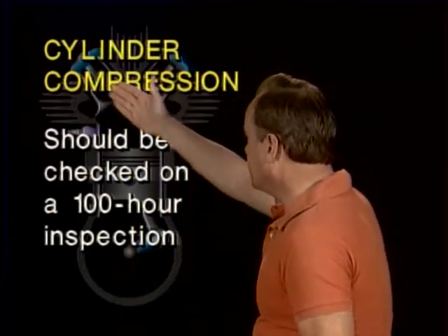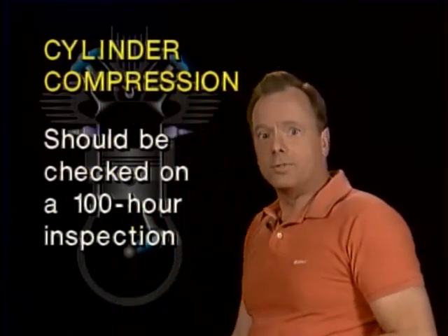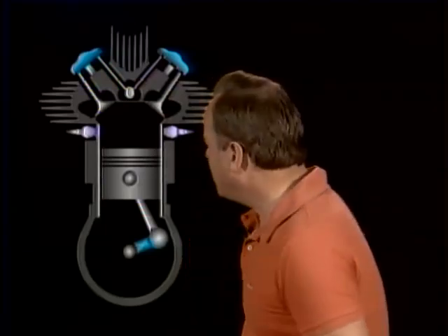How about that? All right, how often, they ask on the test, should cylinder compression be checked? The answer is, on a 100-hour inspection at least, you must check cylinder compression, maybe more often if you think you have a problem. Let's assume you're pulling a propeller through and you hear a hissing sound from the exhaust stacks. What does that mean? That probably indicates exhaust valve blow-by.